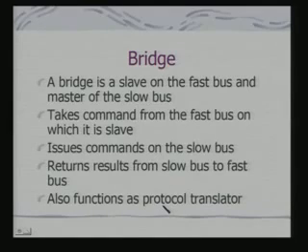So in fact, a bridge you can consider as additional hardware. In a very simple case, a bridge would simply implement a protocol machine, that is a finite state machine, but in more complex cases like the PCI bridge, it will be as good as a controller with its own registers and control logic.